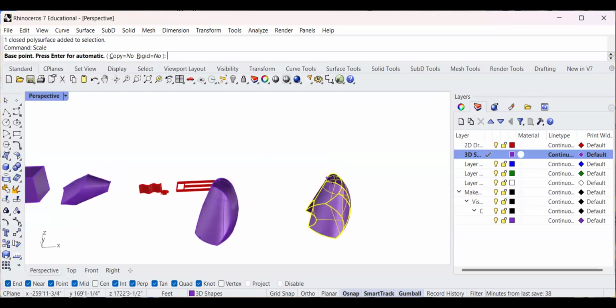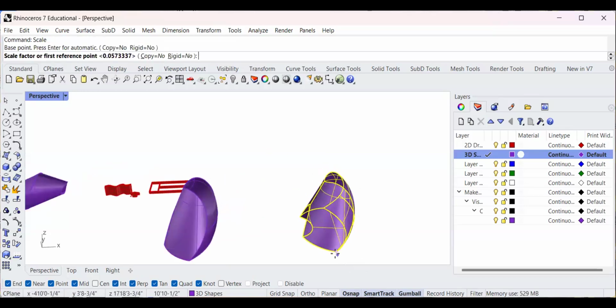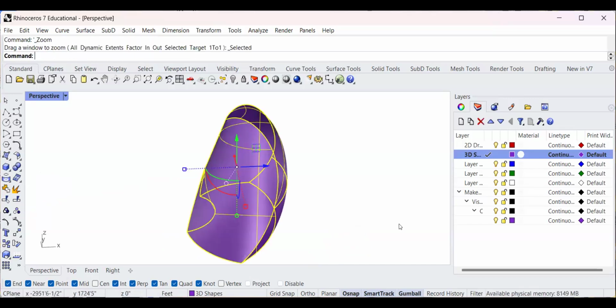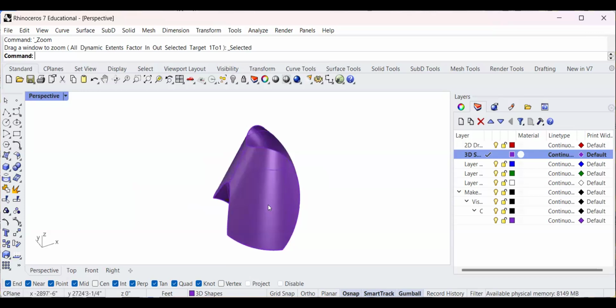But this time, I'm going to select a base point, and I know Ruben's gone over how to do scaling on CAD. Same idea. So let's say if I want to do 1/8 scale, then I take 8 times 12. So it is multiplied by 12. So that's 96. And then find the reciprocal. So it's 1 divided by 96. So I can type in 1 divided by 96, and that's my model in scale.